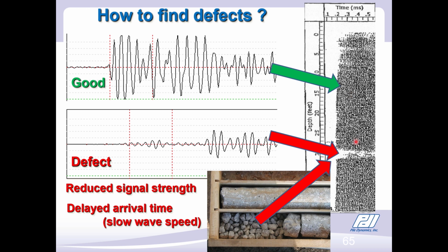This particular shaft was cored, and this is the coring result, and you see that that's not what you want. We had a segregation problem there, probably caused maybe by a tremie issue in the drilling of that shaft.